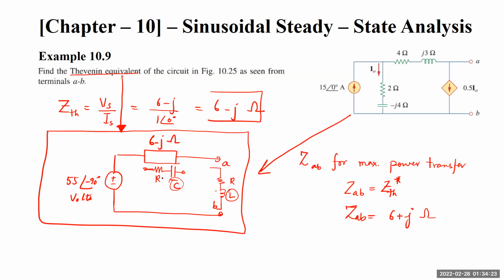In that manner you will have a purely resistive circuit, there will be no back and forth flow of power, and whatever your source is supplying, maximum power will be delivered at the load end. This concept is extensively used in many different circuit analysis techniques, especially when it comes to antenna design or matching concepts in microwave circuits.